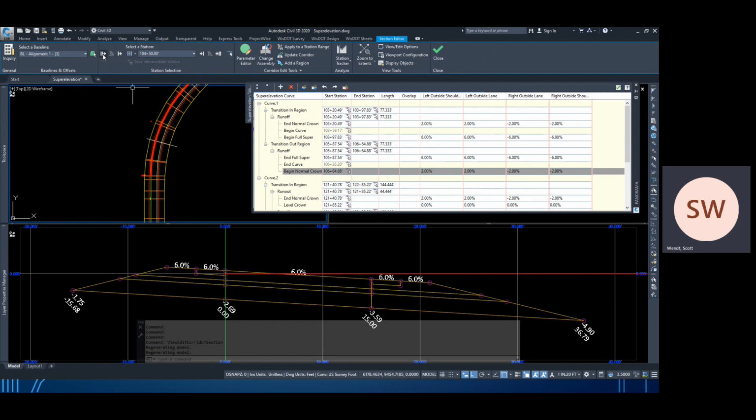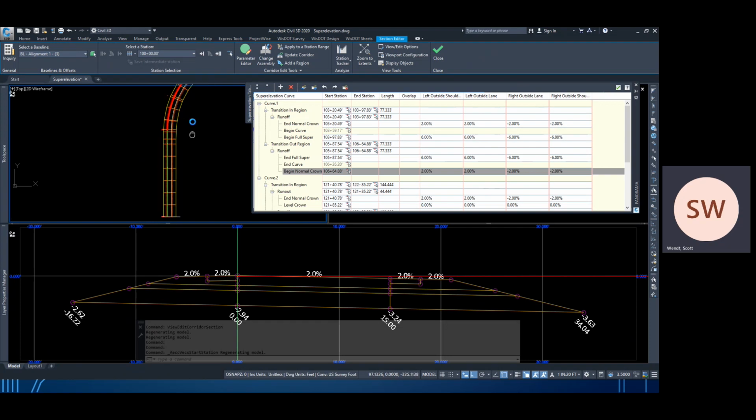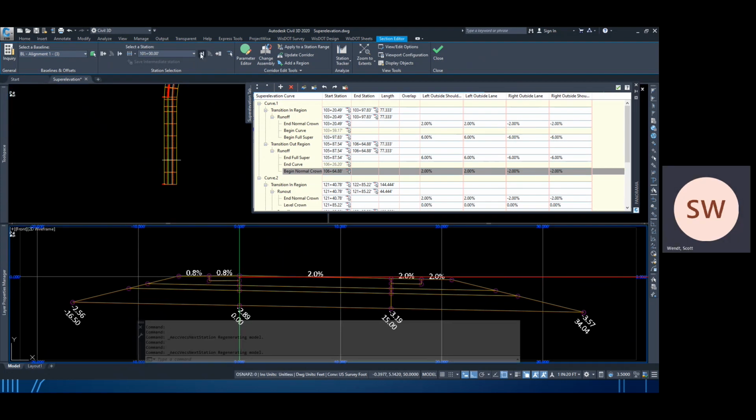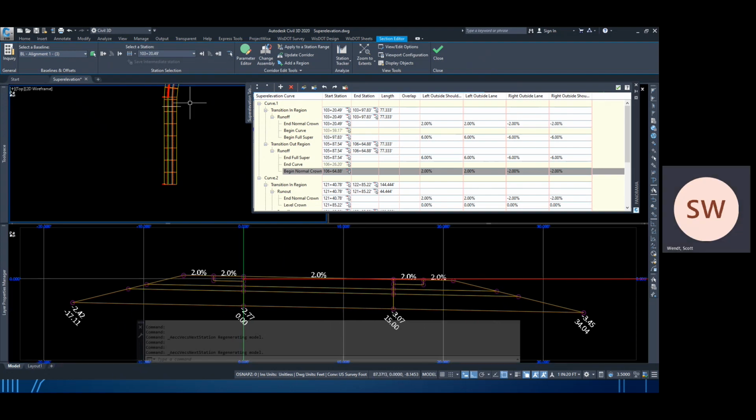We're going to go back to the beginning to see our rotation. And the first thing I notice here is our shoulder slope is rotating down where it should be up. So we're going to keep an eye on that, see if that's happening to our other curve as well. We're going to step through. Our shoulder is rotating. So now we're at 2% planar. So we're going to have to take a look at this area and come up with a picture of that.